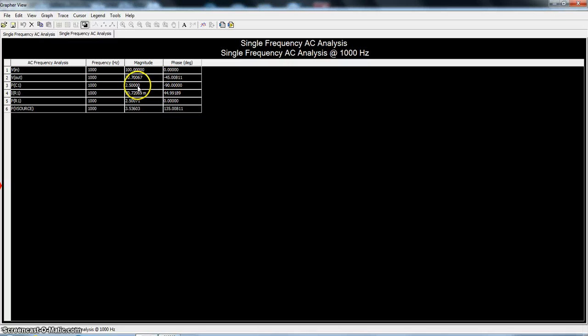The power associated with the capacitance is, again, reactive power. It's 2.5 at minus 90 degrees, meaning it's minus J2.5. Reactive is minus 2.5 bars, volt amperes reactive. The current in the circuit is 70.7 milliamps at an angle of plus 45 degrees. The power associated with the resistance is 2.5 at an angle of 0, meaning it's real power.